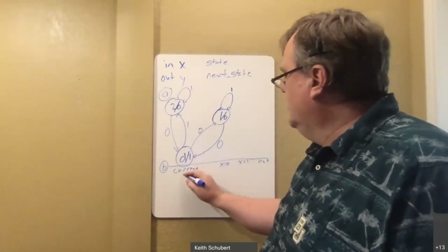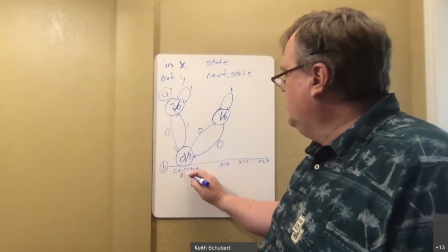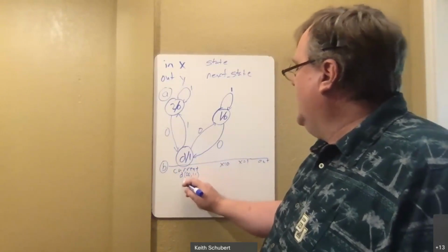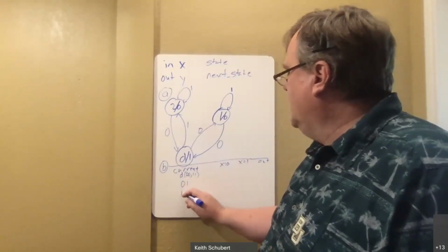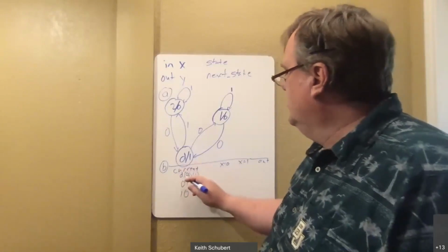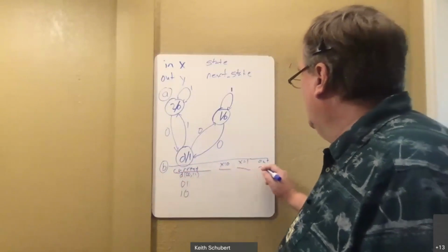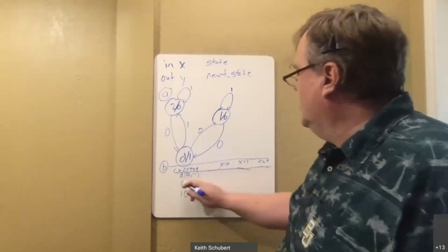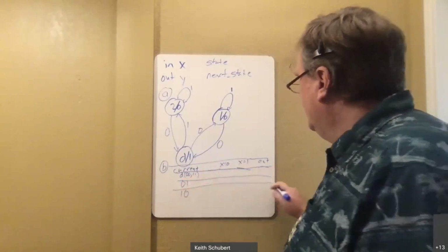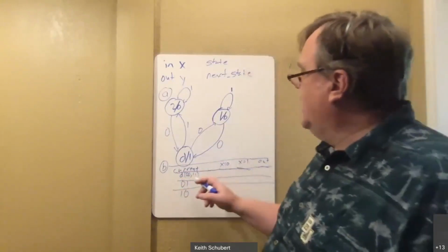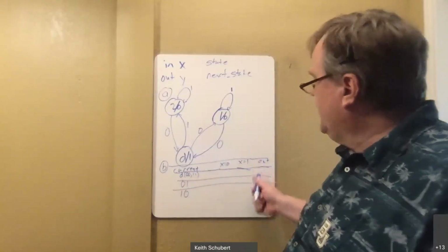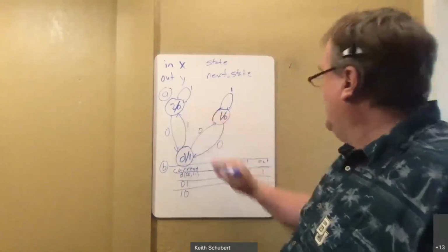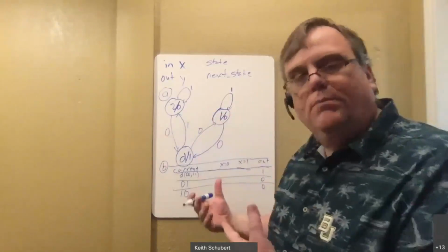So my current state in here could be my default, which is 0, 0, or 1, 1, either of those. And then I've got, if my current state is a 0, 1, and if my current state is a 1, 0, which is 2. I'll just continue this line across straight, and I'll do one line for each to keep them nice and separate. All right, so now all I have to do is walk to each of these states. I'm going to fill the output in first because it's really easy. The default has an output of 1, and the other two have outputs of 0. The output part is done.